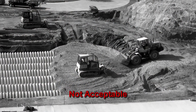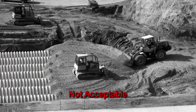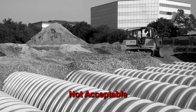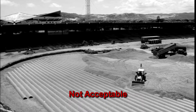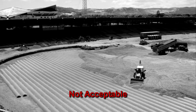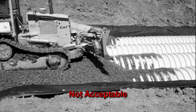The dump and push method is the placement of embedment stone around and above chambers by pushing stone with construction equipment, such as with dozers or loaders, prior to the stone being placed between chamber rows, perimeters, and over the top of the chambers. Dump and push is not an acceptable method to place embedment stone, and any damage to chambers resulting from the use of this method will not be covered by the standard ADS product warranty.